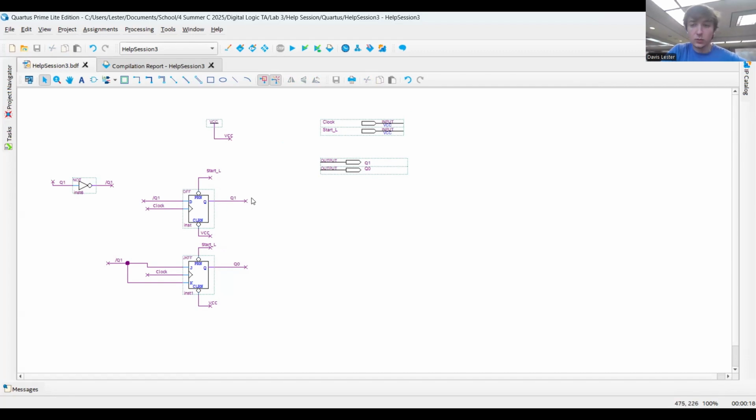So basically how this works is in your exams, practicals, wherever, when you're going to go and draw a functional block diagram, you wrap around Q1 coming out of the flip-flop into some sort of mystery functional box that does logic. In this case, we just have a simple inverter gate, but in other times you're going to have some complex logic, and you come out, and that's going to go back into the flip-flop.